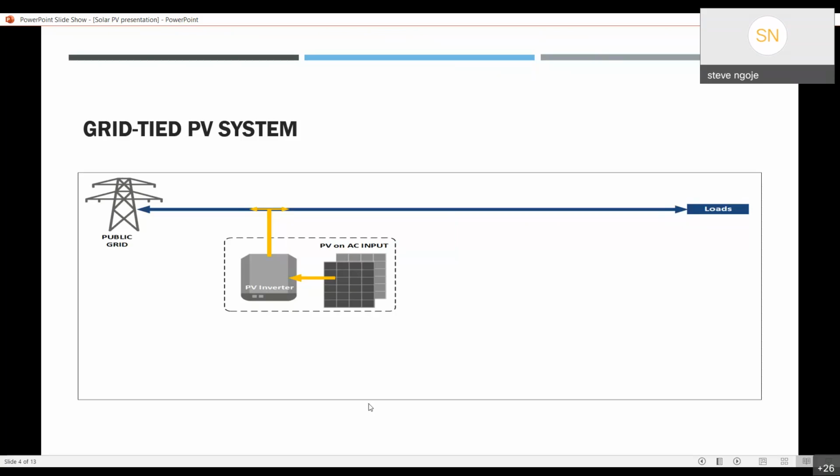So for example, back to my example of the 100 kilowatts, if for some reason your loads go to zero, the grid is available, it's midday on a very good sunny day, the general weather is good for PV production. The inverter will reduce its generation from the 100 kilowatts that it would have been able to give you to zero. It will stall, really. So we are not allowed to feed back to the grid. So that's something that, again, you have to consider during your designs.